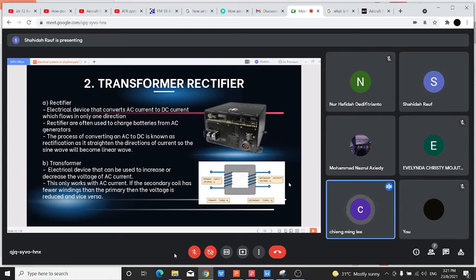When lightning strikes, the static energy will discharge through the static or electrical dischargers at the wingtip of the aircraft, or once touchdown. You will not store it on the aircraft itself. That's why the aircraft is fully bonded.